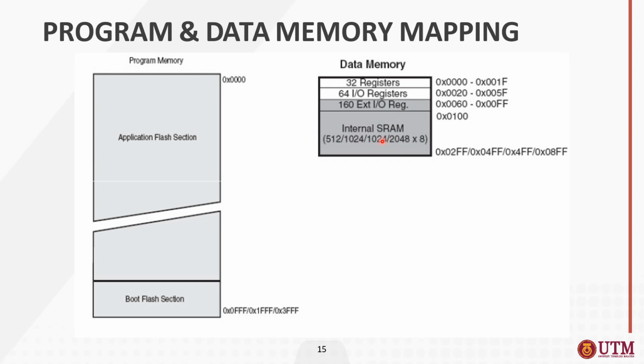Right, so for example, you have ultrasonic sensors, and the distance data that you get from the ultrasonic sensors is saved inside a variable called distance. The data inside the variable distance will disappear after you switch off the device, because it is being stored inside the static RAM. For the Atmega328, there is a total of 2 kilobytes of SRAM.